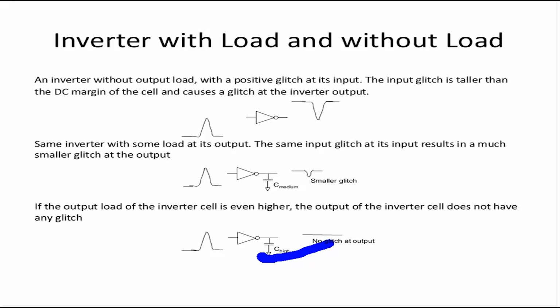It can cause a big noise on this net, and although it won't affect any logic value at first glance because it is not driving anything, this glitch can cause some other coupling capacitance effect. That is why the output of any cell should not be left open. It should be either grounded or tied to a load, or the cell removed.